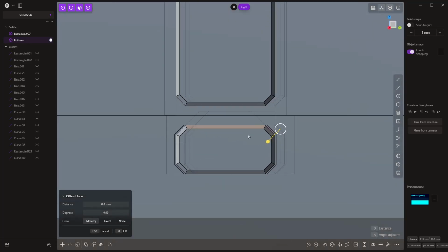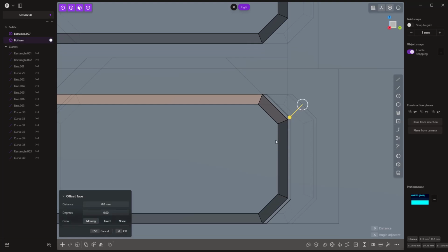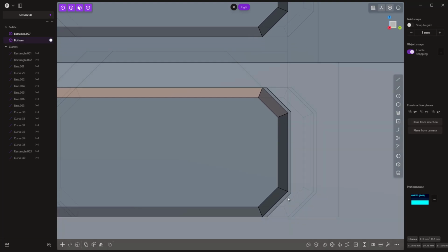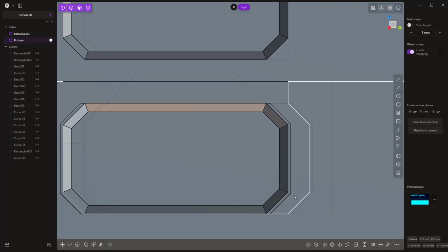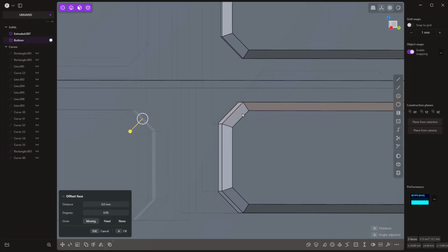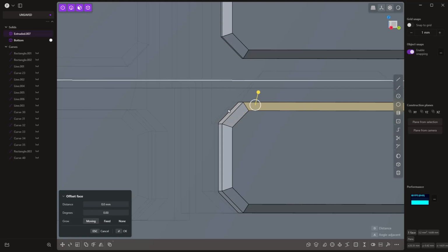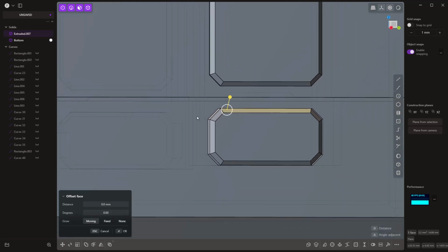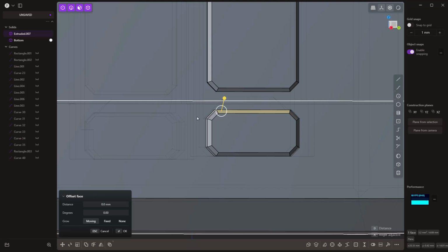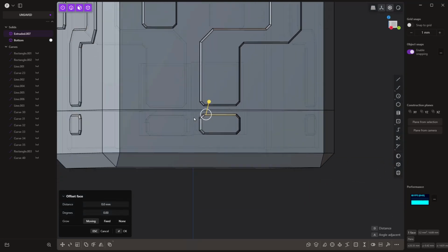Let's go ahead and look from here. So top and bottom exactly match. The sides now have a small gap, which will allow it to move a little bit. And because of the chamfer or that taper on the outside of these, it should help us align. One of the good things here is we can always sand or file or trim down the plastic a little bit if needed. We can't really add more plastic back to it after we've printed it. So generally I err on the side of caution and make things a little bit tighter, knowing that I can drill holes out or I can sand things down to make them fit a bit better.